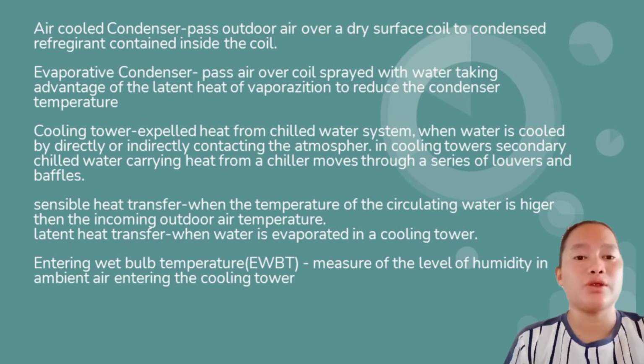Air-cooled condenser. It passes outdoor air over a dry surface coil to condense refrigerant contained inside the coil. Evaporative condenser. It passes air over a coil sprayed with water, taking advantage of the latent heat of vaporization to reduce the condenser temperature.